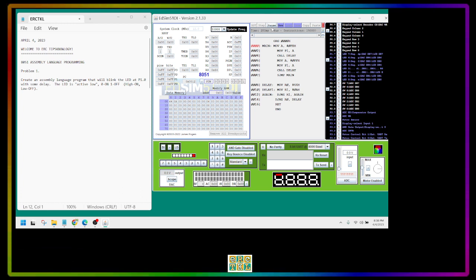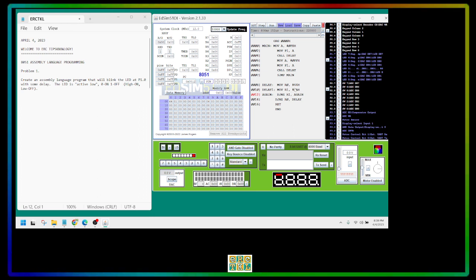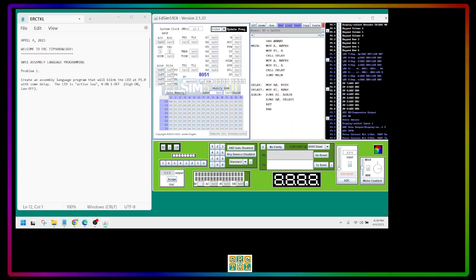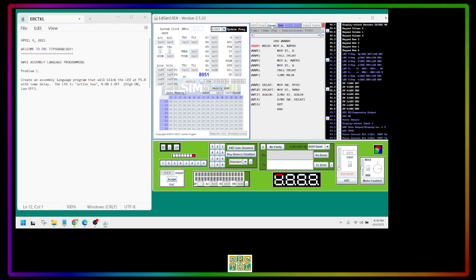Okay, so now let's pause and check on the delay. The delay is MOV R0, #64H, MOV R1, #08H, DJNZ R1, again, and then DJNZ R0, delay, but this should be delay 1, not delay only, but delay 1. And I think this will now be okay. Let's click assemble. It's okay, run. Yes.